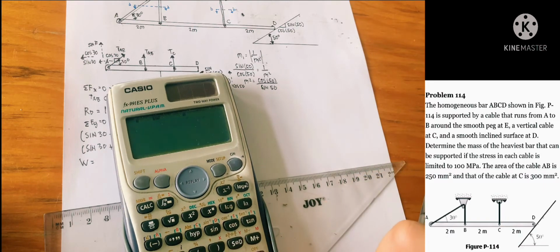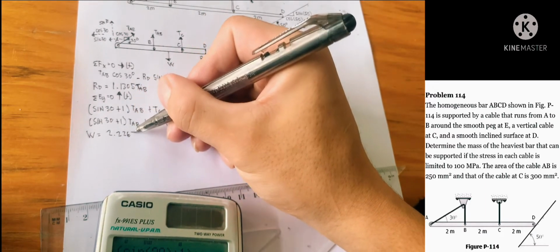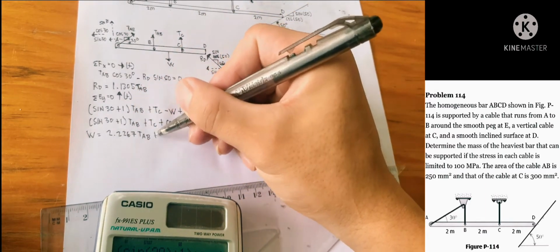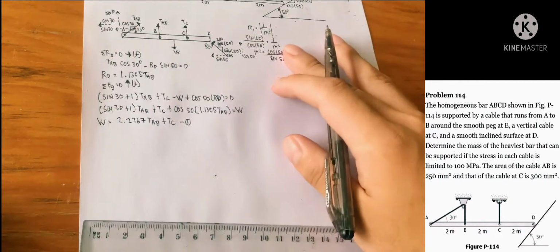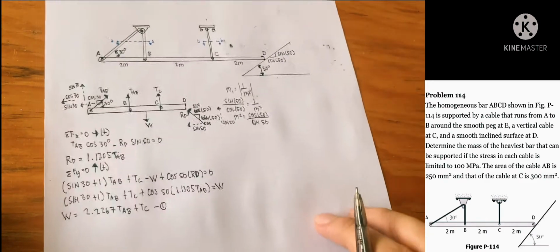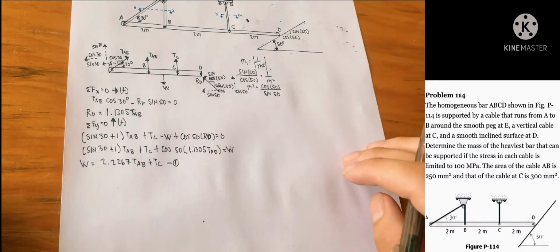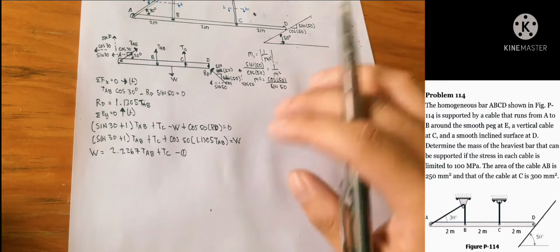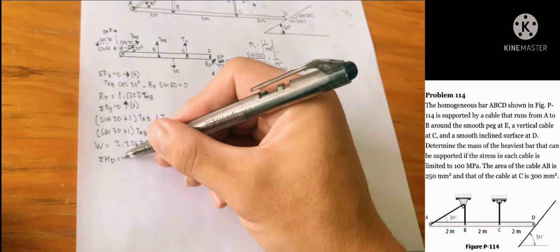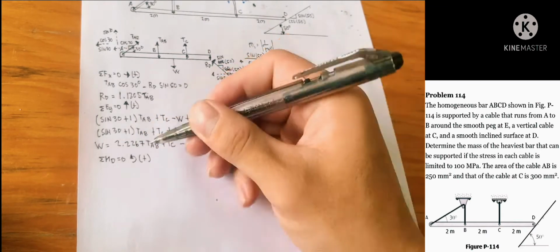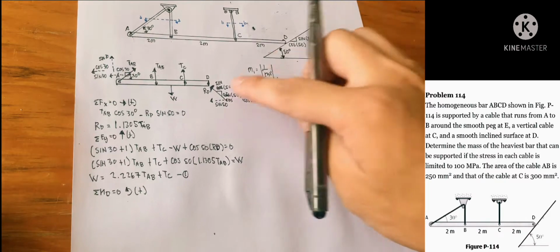By the way, if you notice, most of our problems would have the same number of unknowns as the number of cables, the missing forces. In this case, it is cables. So we have 3 unknowns in this equation 1. We can bring out tension of AB and AC by taking a moment at T. We've already reduced the number of unknowns by our first 2